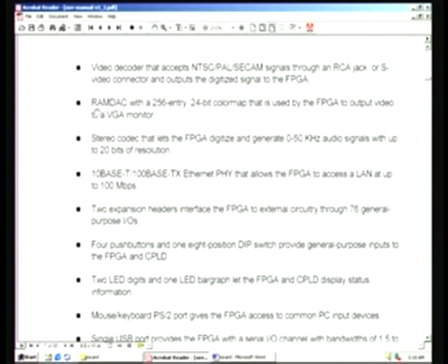And it also has a RAMDAC. DAC stands for digital to analog converter, and this can be used for converting the color of, for example, the NTSC you have received. If you want to display it on the monitor, the computer monitor that you have right here, that is called a VGA interface or VGA monitors. It can be connected through this RAMDAC chip, and it has some 256 entries available, and that much storage is available on this, and you can configure for true color, say 24 bit color map you can configure,